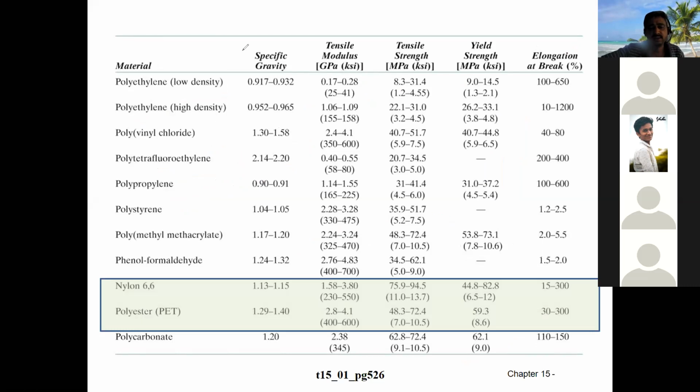So what happened is that the tensile strength is very high in nylon because it can have a higher percentage of crystallinity in this material, which is not allowing the material to break. Why you are getting a low yield strength is the amorphous nature of nylon, which gives a plastic nature to the material. But the strength is coming from the crystalline part.